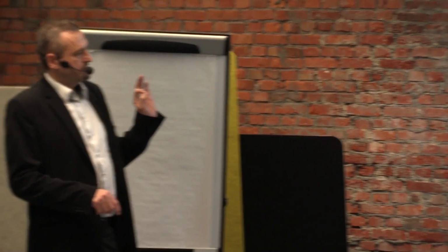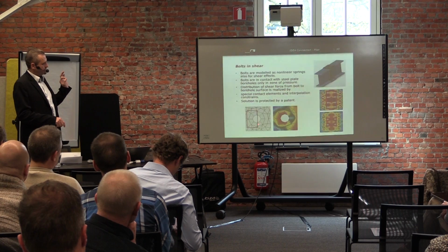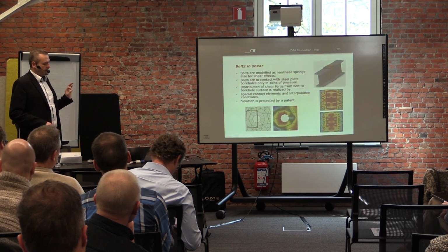around this opening. You see this is a predefined mesh here, and in fact our bolt is only a spring. It's a one dimensional element, and we connect this point with these points at the edge of the hole and around the hole.